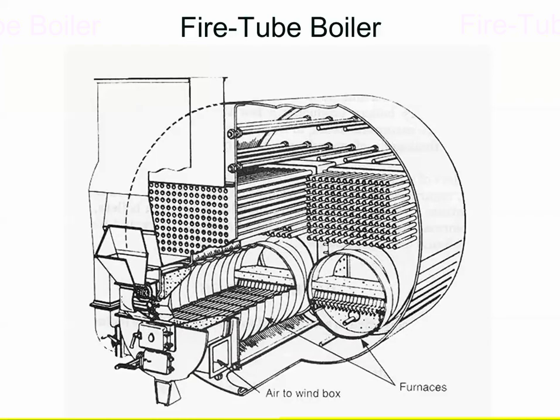This drawing is of a fairly antiquated boiler. This was a coal-fired one, and you would open up this door right here and literally shovel coal onto this grate and rake it so it's fairly flat. The ash would drop below the grate, and you open this door and pull on this handle, and there was a steel kind of like a fork in the back that, when you pulled it forward, would pull the ash towards you so that you'd shovel it out.